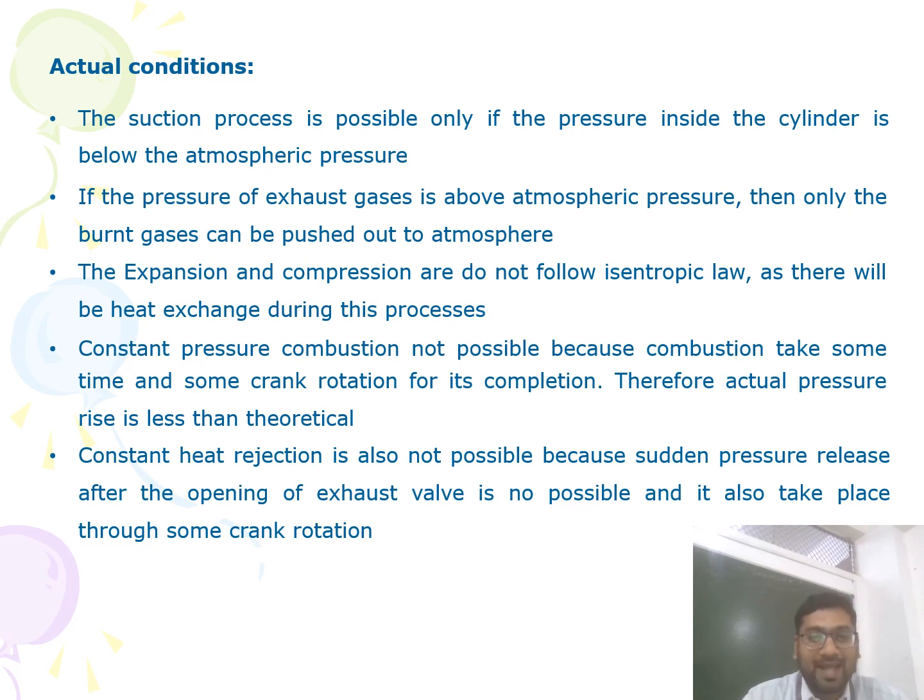And third, the expansion and compression do not follow any isentropic law, as there is always heat exchange during all these four strokes. For an isentropic process, there must be no heat interaction. Only in that condition will the isentropic process be carried out. But during the working of an IC engine, or any four-stroke petrol or diesel engine, there is heat interaction between the atmosphere and the IC engine. So that's why it is never carried out isentropically.